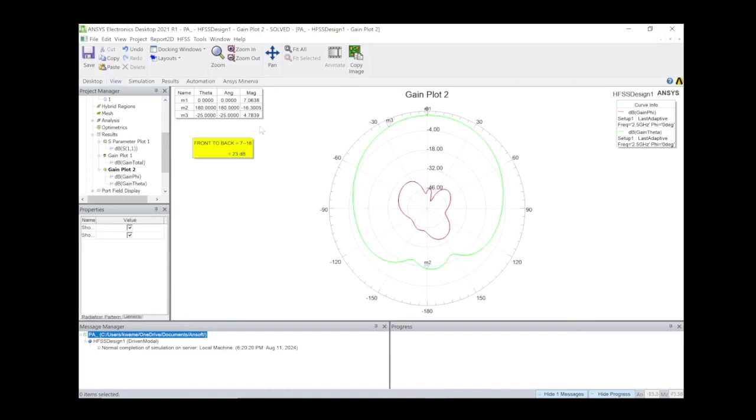So with the half power beamwidth, we are looking at 3 dB less this value. Okay, so we will be moving. That value was 7 point something, and we had 4 point something for this one. So we have 5. So we have 5 over here. Okay, 4.6. So we can place our marker here.